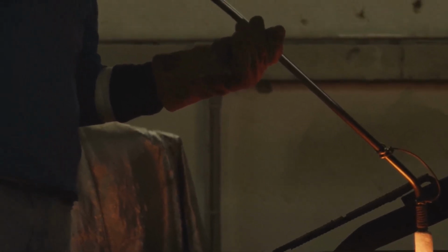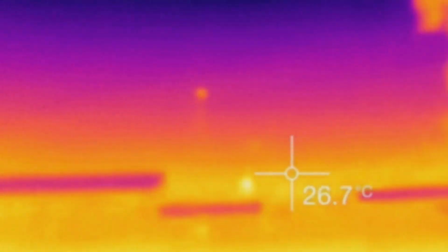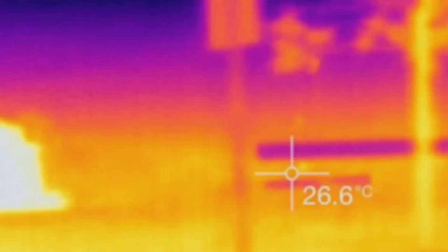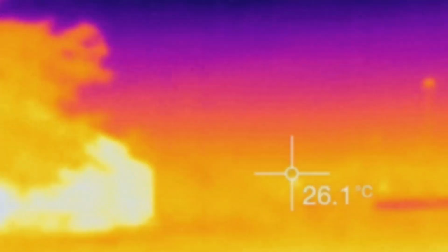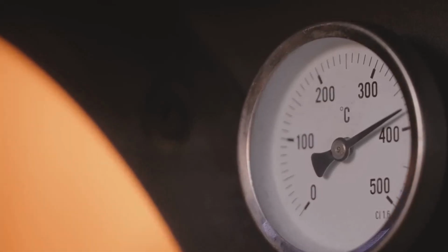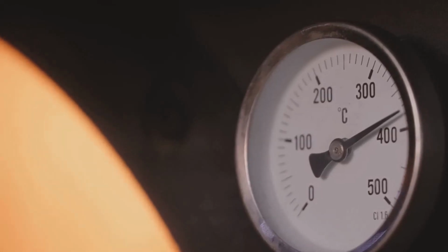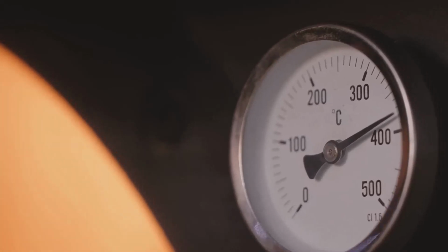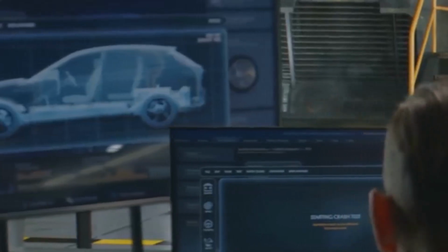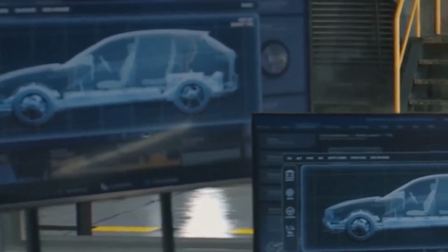Of course, using a high Y+ value with certain turbulence models is like holding the thermometer an inch away. The software has to use a simplified model to estimate the temperature at the surface. But when Y+ is around 1, you're placing your virtual thermometer right on the pan, getting a direct, accurate measurement of the physics at play. This direct resolution is the gold standard for many applications.